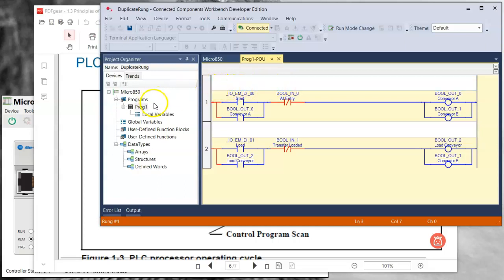So when this program starts and it's running, it goes to rung 1. It scans across from left to right to try to solve the logic, or find a true path to get from here to the other side of the rung, essentially. And if there's no true path, then these two outputs would not be on, told to still be 0.